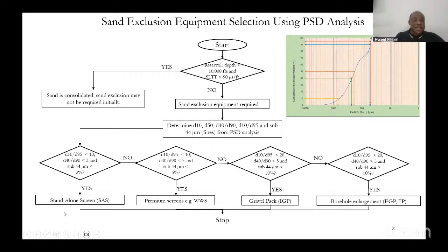So you can use standalone screens, depending on this analysis. You can use premium screens. You can use gravel pack. You can use open hole gravel pack, frac and pack and so on, depending on the outcome of your analysis. You also use this particle size distribution data to design those sand control mechanisms.